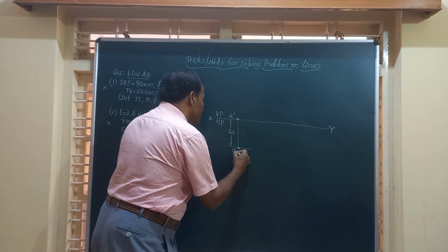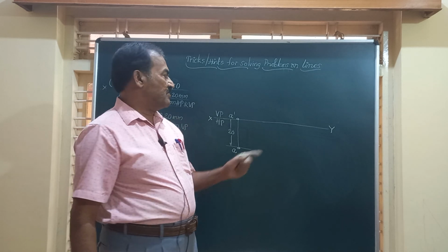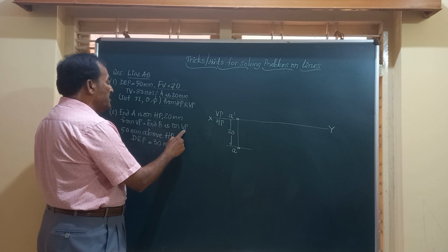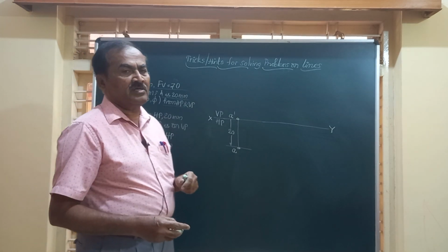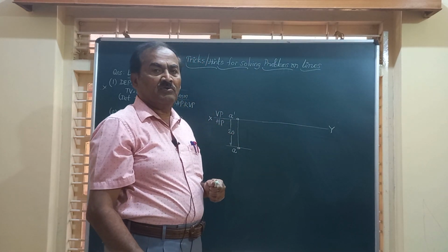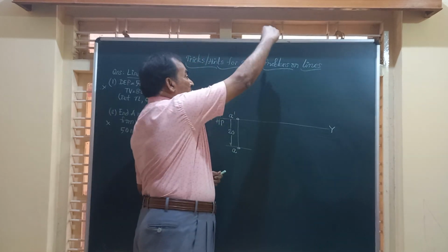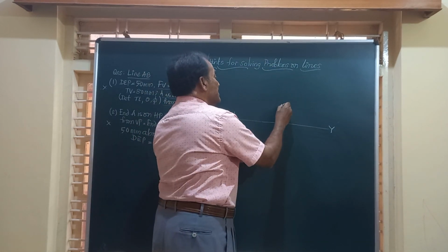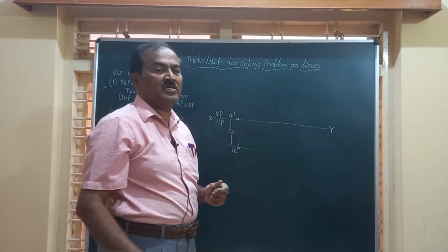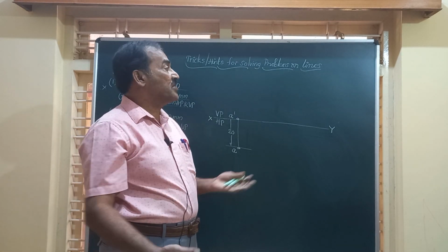This is going to be the point A, the top view of the end A. Front view is A dash. Friends, now the end B is on VP. So whenever a point is on VP, on this board, friends, the front view is seen above the XY line, and the top view, wherever the point is, when you look from the top, the shadow of that point falls on XY. That is, the top view will be on XY. So this is the way to draw that.